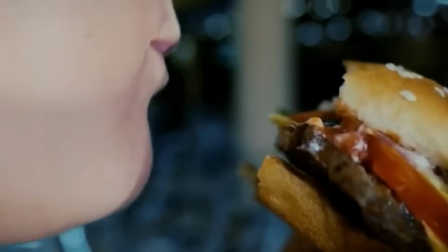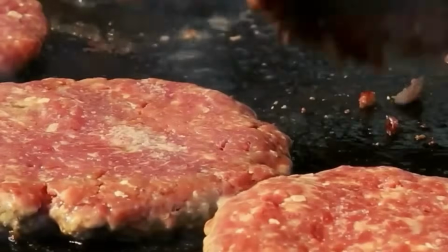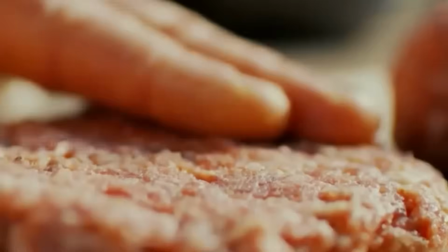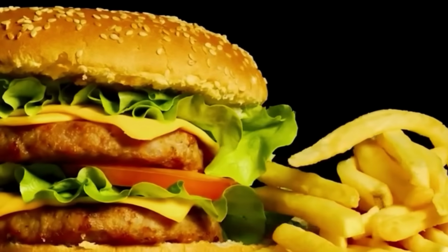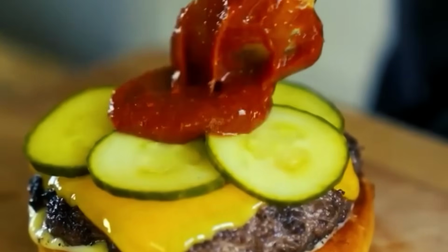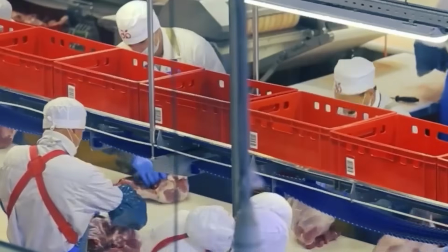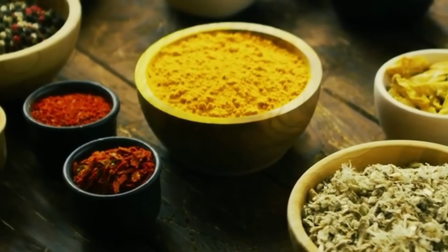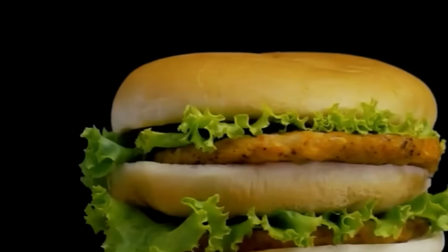Internal temperatures of patties are monitored via embedded thermocouples in test units during hourly quality assurance checks. Each patty must achieve an internal temperature of at least 71 degrees Celsius before being passed to the holding area. The broiler is equipped with grease drainage systems that collect rendered fat into heat-resistant trays, which are emptied and cleaned daily. Cooked patties are deposited onto a stainless steel chute that guides them into heated holding trays.